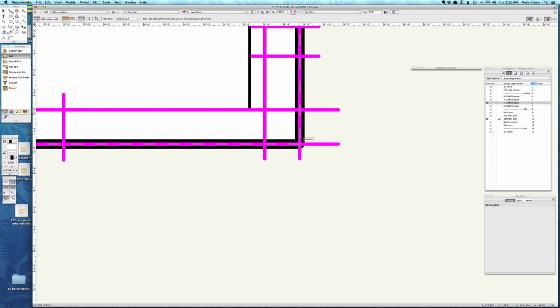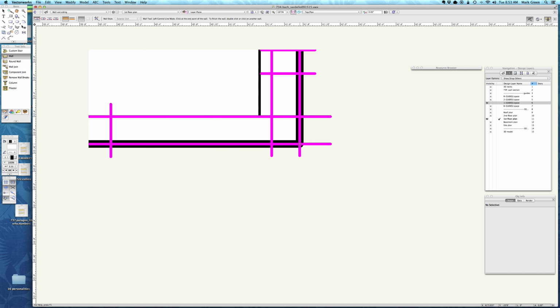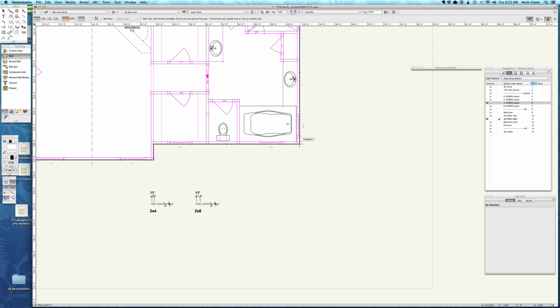I'm on right there. So just going to click once and let go, and I'm going to zoom out. And if I hold down, you can see that I can draw the wall at any angle. If I hit the shift key, that locks me into drawing either 90 degrees, 30 degrees, 45 degrees, whatever.